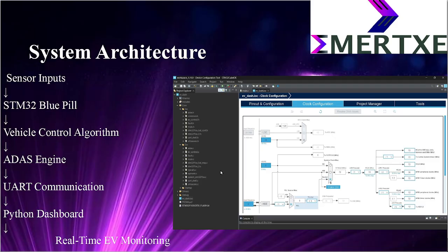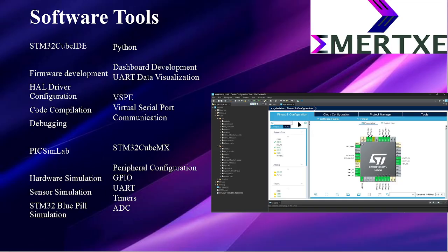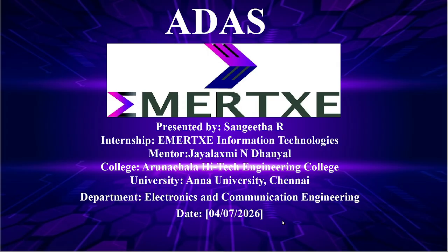This is one of the workspaces of STM32 IDE. This is for the Cube configuration. You can see this is the Blue Pill board, the microcontroller board that we have used. This is the pinout configuration side in the workspace of STM32 IDE. This is the total PICSimLab setup that I have done.